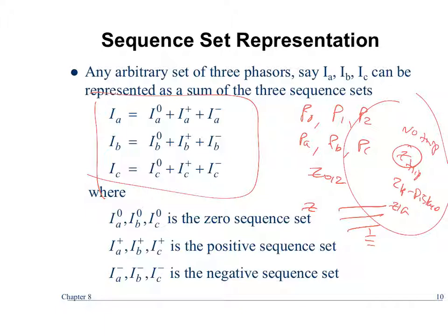What about the ground? It's always changing. It could be here. You have a wire that's touching the ground. It's arcing. So you could have a pretty high impedance there. So the distance element for ground is not great because of that fact. So every time I've set a 21G, I've always set a 67N.